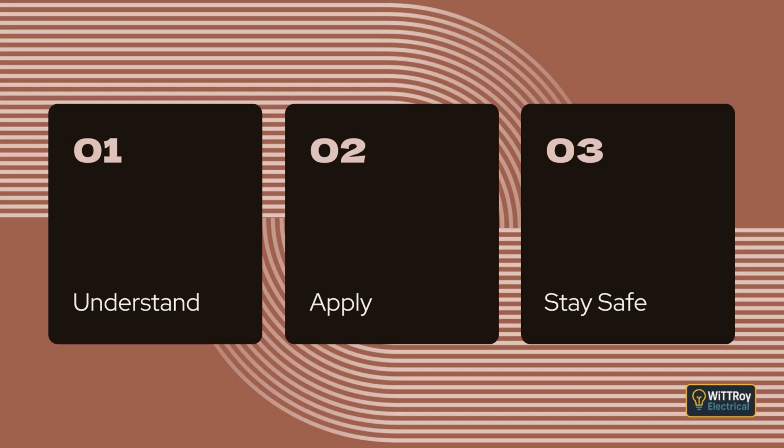Clause 2.9.7 Fire protective measures. Wiring around switchboards must be arranged so that if a fire starts in the switchboard, it does not spread easily. Where wiring enters a switchboard enclosure, the entry points must fit closely around the wiring so flames or smoke cannot easily pass through. In many cases, this means using close-fitting openings or fire-resistant sealants. Large openings may need sealing to stop the spread of fire. Internal conduits or wiring ducts inside the switchboard also need sealing if they could allow fire or hot gases to move inside the board. Now that brings us to the end of Section 2 of ASNZS 3000.